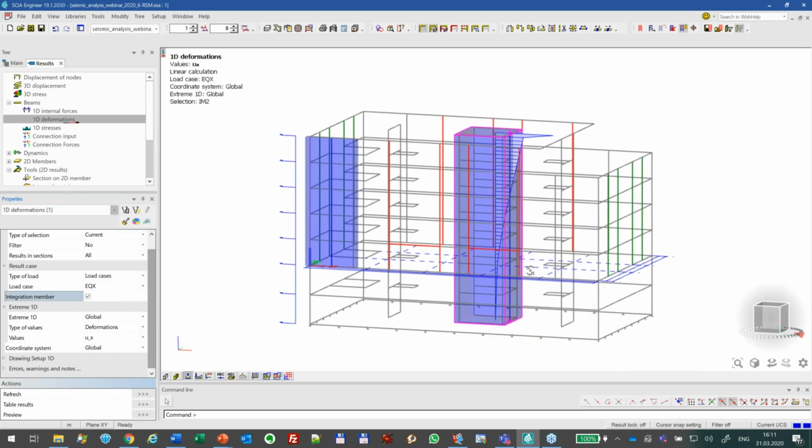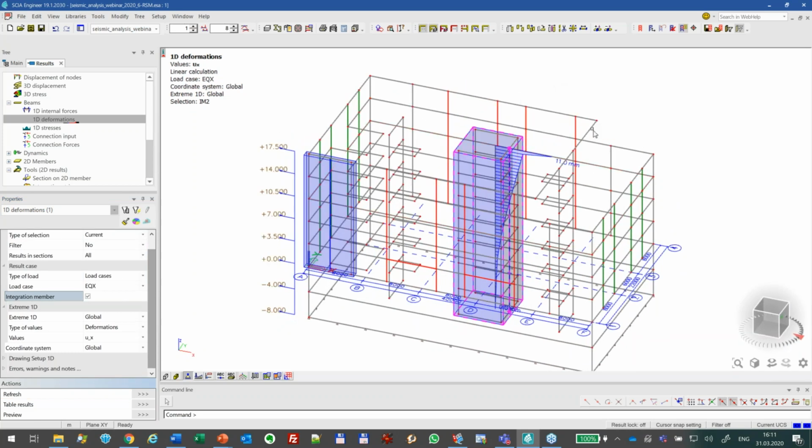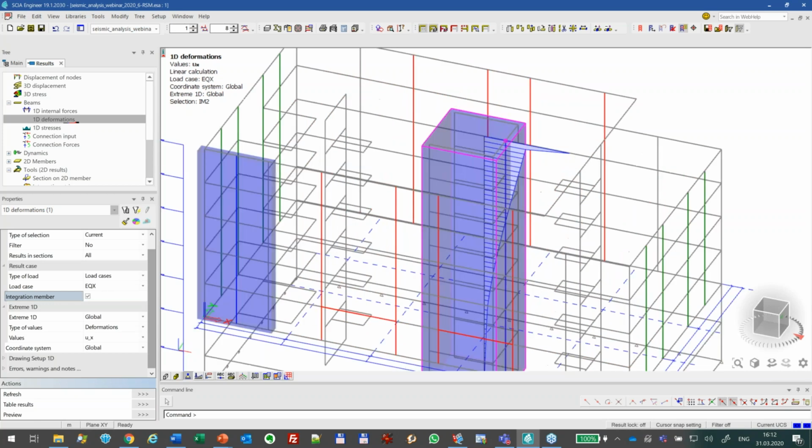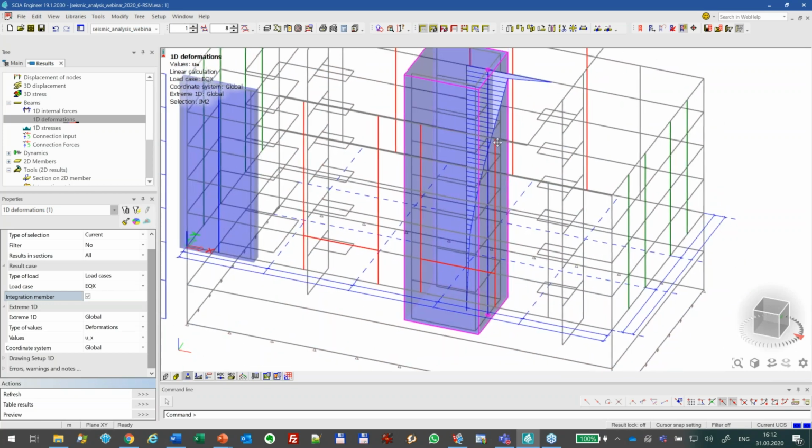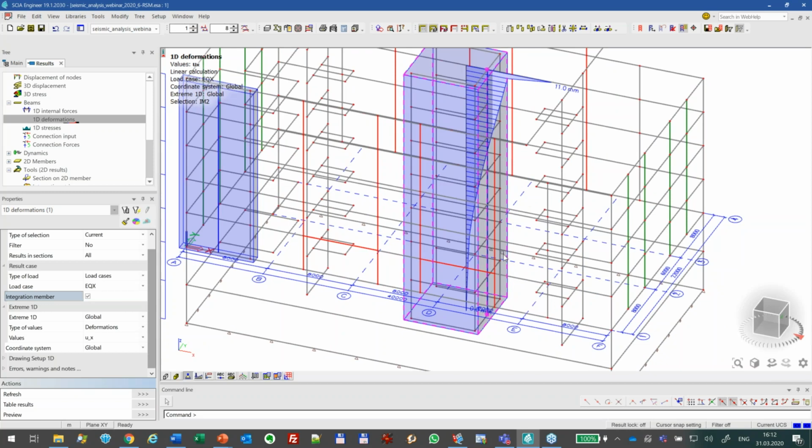Okay, there is a peak at the top because the connection of the top of the roof actually is not perfect. There is, you remember, the sliding aspect of the masonry walls, and that creates a slight discontinuity. There are actually fewer shear walls connecting the top slab. So that explains that little jump here. But you can essentially obtain also average displacement values throughout a number of elements in this way.